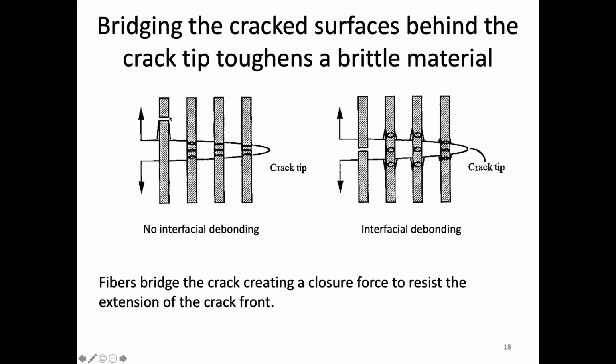Well, let's say we now have these fibers in the material, very long particles here, sort of along perpendicular to this crack tip. So in that case, when we expose this to mode 1, right, so we're basically trying to pull this and extend this crack apart, it wants to open, there's the stress concentration here, and it wants to move towards the right.